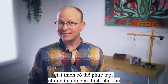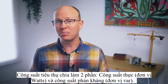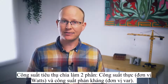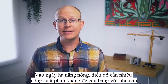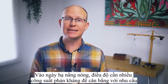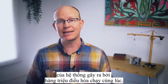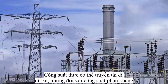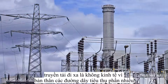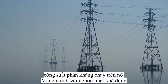This concept is kind of deep in the weeds of electrical engineering, but we normally simplify things by dividing bulk power into two parts: real power, measured in watts, and reactive power, measured in VAR. On hot summer days, grid operators need more reactive power to balance the increased inductive loads on the system caused by millions of air conditioners running simultaneously. Real power can travel long distances on transmission lines, but it's not economical to import reactive power from far away, because transmission lines have their own inductance that consumes the reactive power as it travels along them.